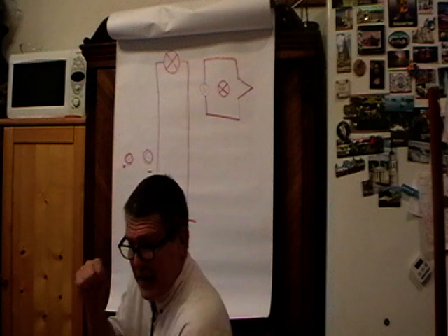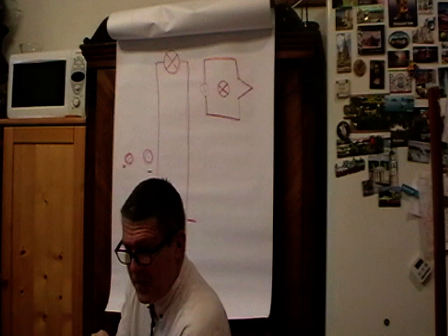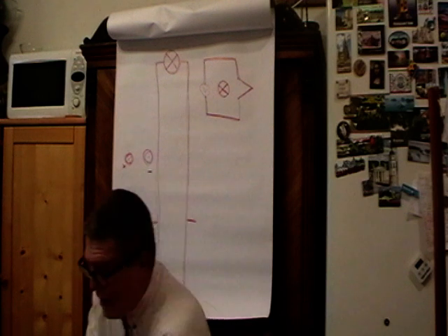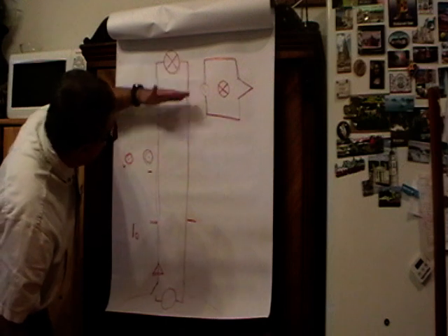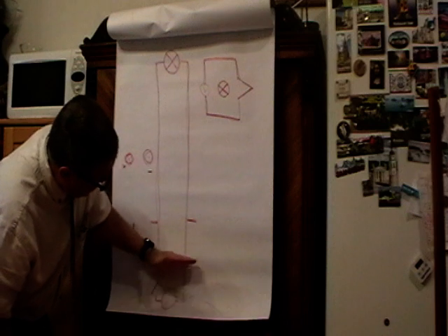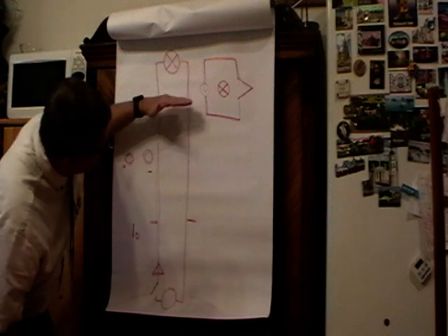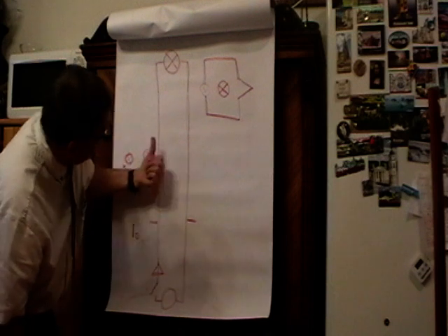And this could be done only if there is a reflection. So that by the moment when the wave reached the valve, the whole line is at voltage V, and there is flowing a current I0 that is charging the line.